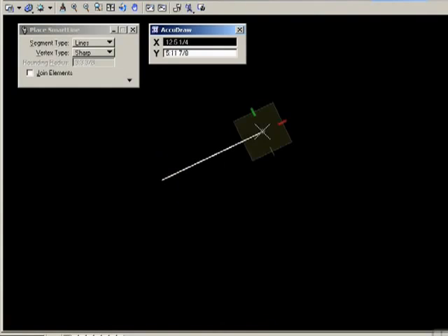But as soon as you data point and the compass moves to the end point of the line, the compass, of course, aligns with the line, and the x and y axes are not those of the view window or the design. They're simply the x and y axes of that drawing plane indicator. That can be a little confusing because, for example, if I move my cursor vertically, I'm seeing a 0 x value in the AccuDraw window, which is not true for the drawing itself. It's only true for the compass itself. That takes a little getting used to, but you'll see how this works out quite nicely later on.